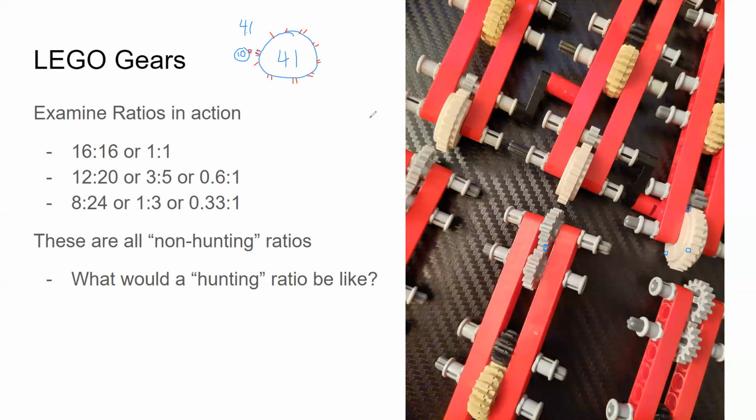And the idea here, what happens in practice is that having one bad tooth mesh with all these other healthy teeth, it hammers out the problems on that one bad tooth and it makes it better again.